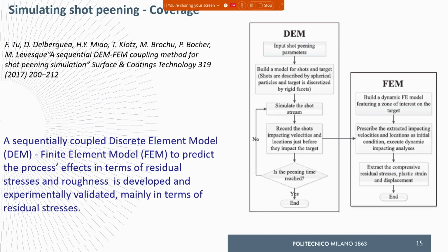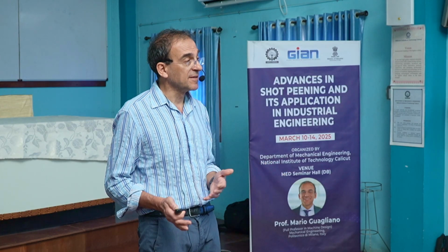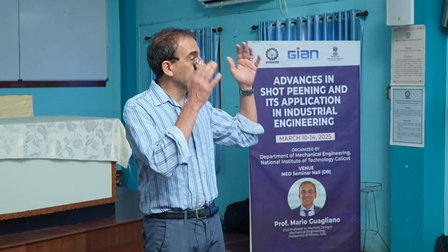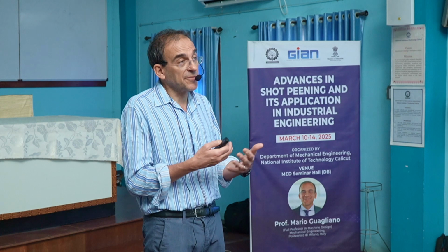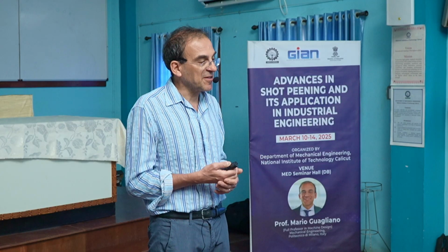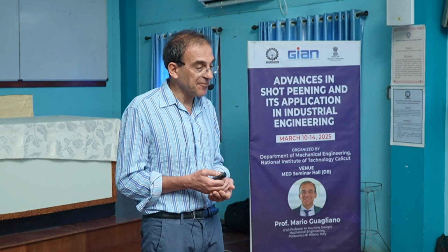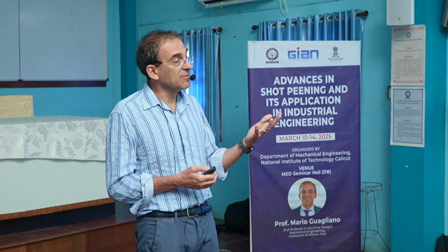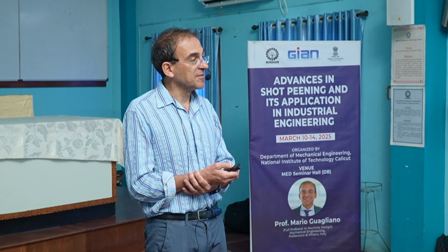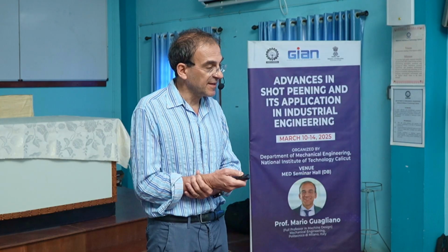Okay, is it clear? So the DEM is not an alternative to finite element. It's something that is adding more information. We can simulate the process itself in a more realistic way with many particles, without so much limitation. This is due to the computing power of the computer today. In the end, we have to deal with rigid bodies in this case at least. And so the result is then passed as an input for the finite element model to repeat the analysis that I have described in the slide before.